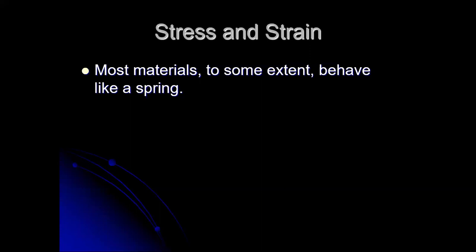And just like stress, it's an internal value. It's not something that we'd measure out in inches, because inches is a physical measurement that requires that we measure something on the outside. Instead, what strain tells us is how much each inch grows. It's a ratio. It says that each inch is going to become a thousandth of an inch bigger. So if I've got something that is 20 inches long, I can predict how much longer overall it's going to grow. If it's 6 inches long, I've got the same ratio. Each inch grows by a thousandth of an inch.